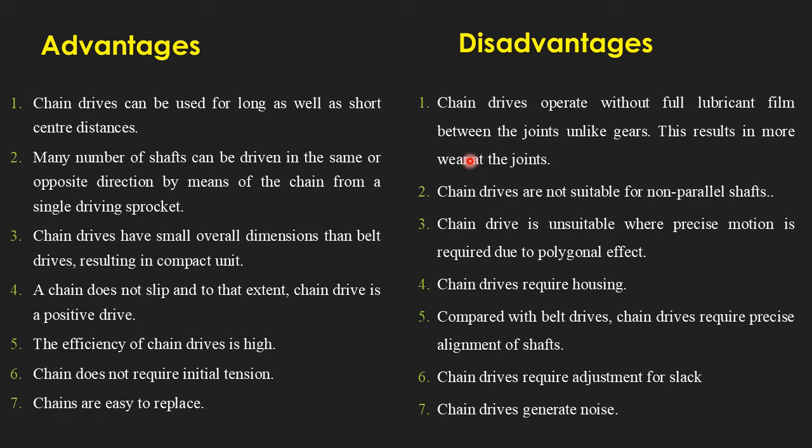Due to this wear, the chain will get extended, and when the chain gets extended, there are chances that it may leave the sprocket. So the tension of the chain needs to be adjusted from time to time, so that it may not leave the sprocket. That is one. And one more is, it is not suitable for non-parallel shafts.